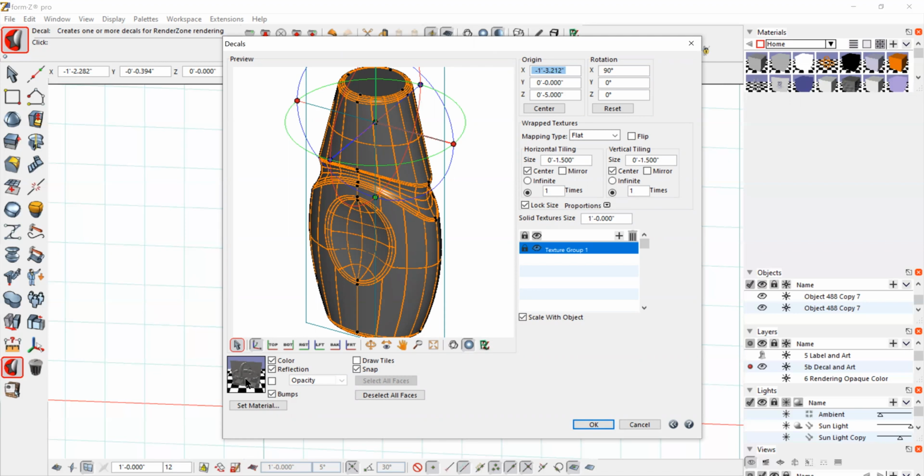If I were to change the color of the body of this bottle, you would see this square sitting on there because it's only a bump map. We don't want that background. We want all the background and the emblem to be exactly the same color. That's why it's critical to do when you do a bump map and you want it to look like an embossing on an object. You need to make the exact same color.